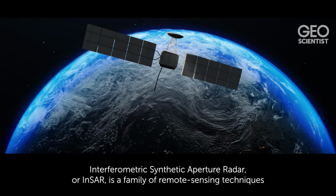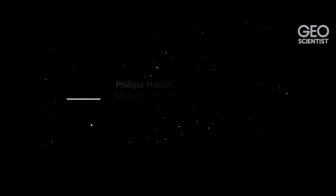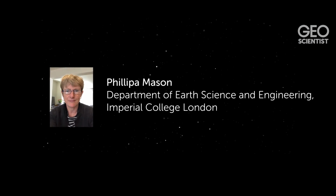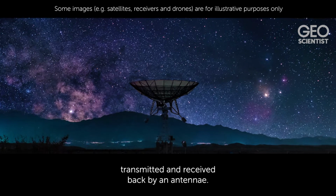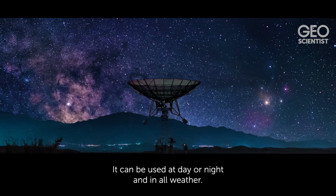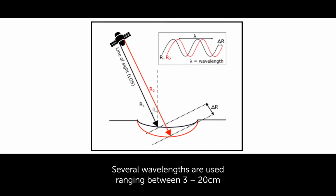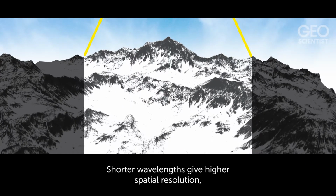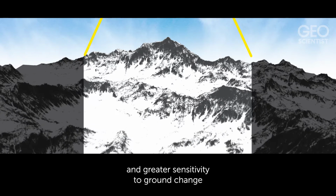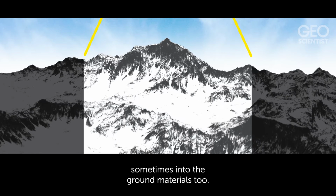Interferometric synthetic aperture radar, or InSAR, is a family of remote sensing techniques used to measure ground deformation. SAR is an active ranging technique which uses pulses of microwave energy transmitted and received back by an antenna. It can be used in day or night, and in all weather. Several wavelengths are used, ranging between 3 and 20 centimetres, referred to as X, C and L band radars, although there are others. Shorter wavelengths give higher spatial resolution and greater sensitivity to ground change, whereas longer wavelength allows penetration through vegetation canopies, sometimes into the ground materials too.